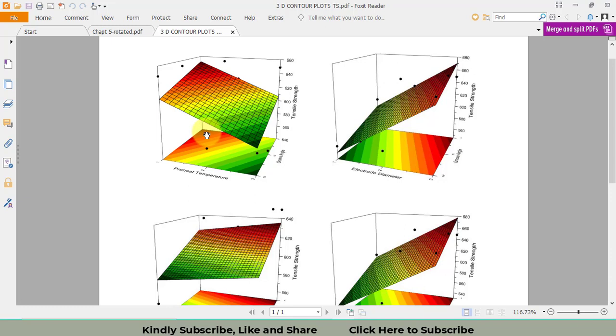Okay, so I have found the effect of preheat temperature in case of welding. I did the welding in my research work. So I want to find the effect of preheat temperature and groove angle on the tensile strength. So the greater the tensile strength, the better our values. Fine. So I say that the first level of the preheat temperature and the first level of groove angle will give me the highest tensile strength, because the intersection of these two values gives me the dark reddish region.